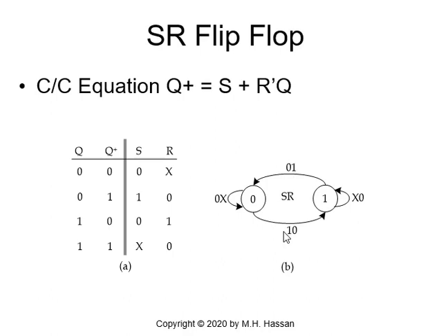This table is extremely important in counter design. And unlike the JK flip-flop, we do not have a shortcut method, because the characteristic equation is not a sum of 2 terms, one for Q prime and one for Q. Here S is one term and the second term is R prime Q. So there is no shortcut method, unfortunately, with the design using SR flip-flops.